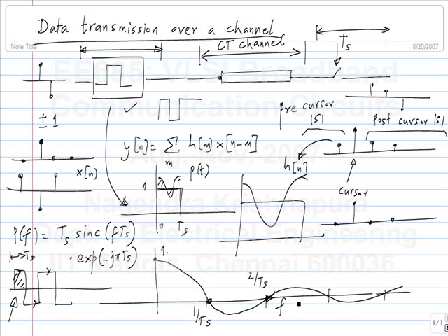And the reason why it is 0 can be seen quite clearly. You calculate the Fourier transform or the Fourier series by multiplying the signal with the sinusoids and then integrating it and so on. So you take a sinusoid at fs and integrate it, multiply it with any phase and integrate it, you will still get 0. Okay. Because you are integrating over a full cycle of the sinusoid.